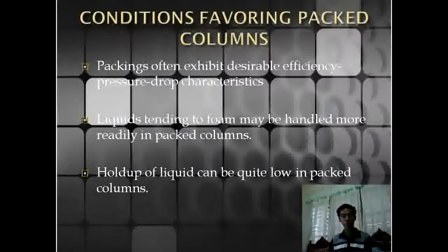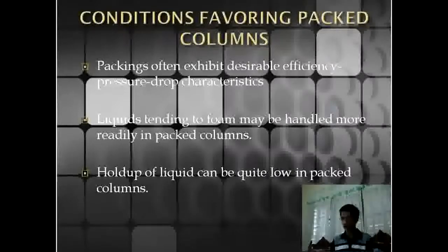Another factor favorable for packed columns is the way it handles foaming. Packed towers can handle foaming because of the relatively low degree of liquid agitation by the gas. Also, holdup of liquid can be quite low in packed columns, an advantage when the liquid is thermally sensitive.